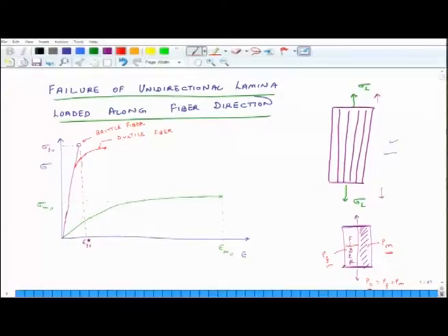Okay. Now, it depends. If the cross sectional area of matrix is very large and the cross sectional area of fiber is very small, then the amount of Pf will be very small, right. Suppose I have only one single fiber in the composite, then the load carried by the fiber will be extremely small, negligible, and that load will get transferred to the matrix and the matrix will be able to bear it. So, then I can still apply more and more load, and once the matrix breaking strain is reached, then the matrix fails.